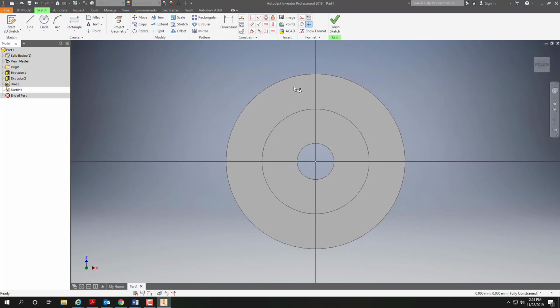Okay, now notice here, looking back at the book, we have an M8 by 1.25, 17 millimeters deep, and there are 8 holes. So how do we do that? Well, again, what we'll do is we will put a point up here and put a point in there. Okay. Now we're going to dimension it.